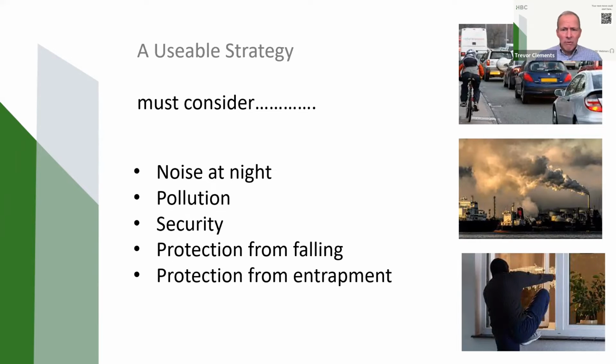There's also the consideration of noisy mechanical ventilation. It's a common problem, and it's covered in approved document F. So there's a cross-reference there. So many people will turn the whole house mechanical ventilation system off if it's noisy, and they'll turn it off in the evening, and then air quality suffers accordingly.